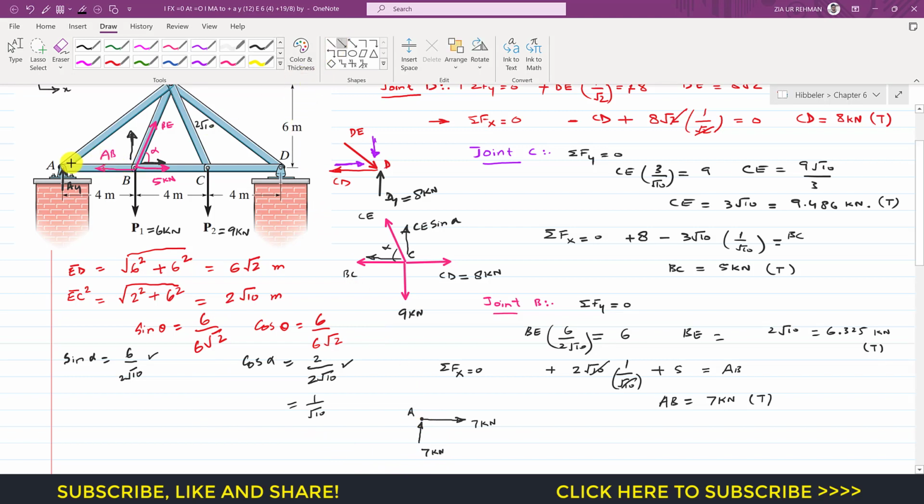And similarly we will have this AE member force, right? So this is AE, let's say it is compressive force. Here this DE member is making theta, so it is also making that same theta, since the truss is symmetrical about that center line, right? So this is that theta. Now if we resolve this AE member force into its components, it will have one component like this, and it will have one component which will be acting vertically downward.